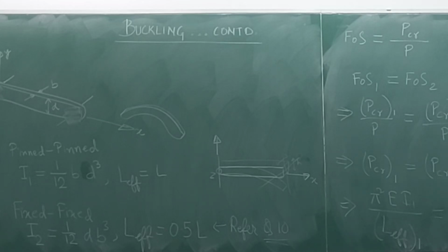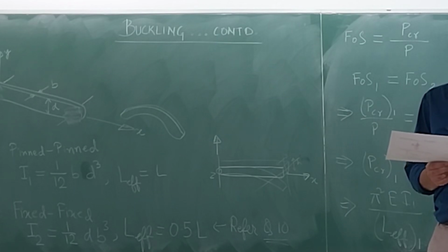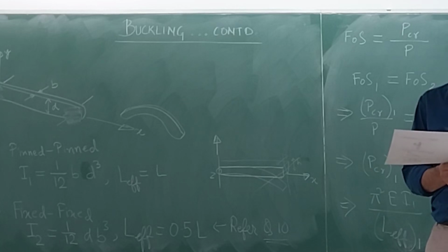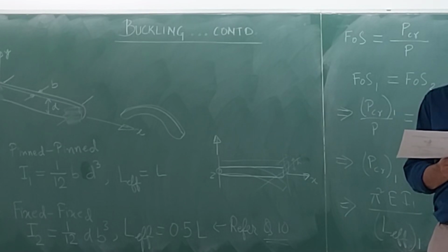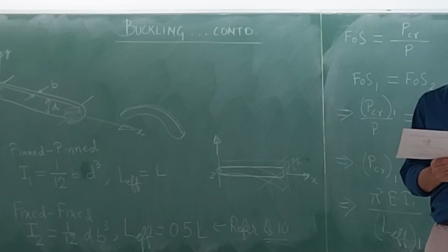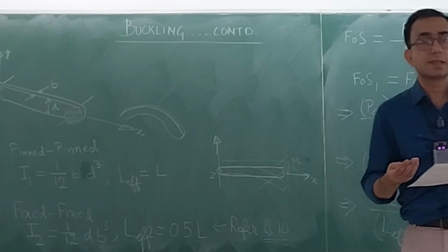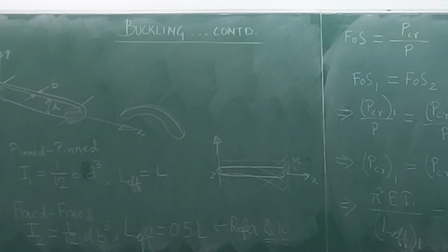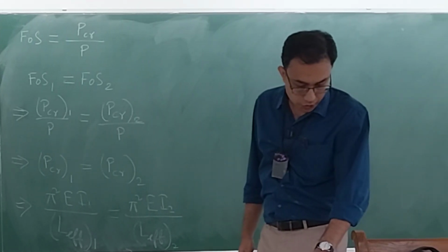So here it is clearly mentioned, right, that each end of the bar can rotate freely about a horizontal axis through the pin. The pin is there, but rotation about a vertical axis is prevented by the brackets. Okay, so the brackets, they prevent the rotation. Prevent the rotation means it's like a clamped or a fixed end. So are you getting the answer here? Okay, so B is equal to how much? 0.5 D, right? I think that's the answer, right? So B is equal to 0.5 D.